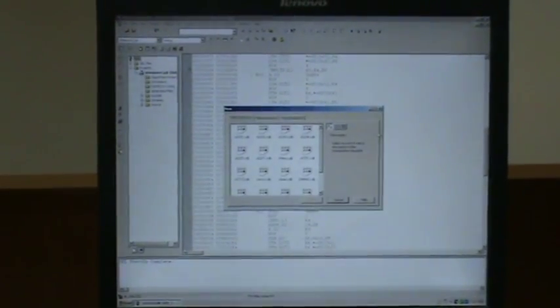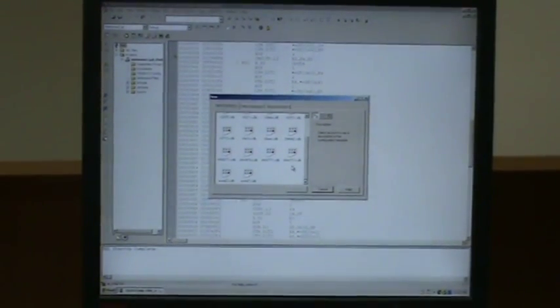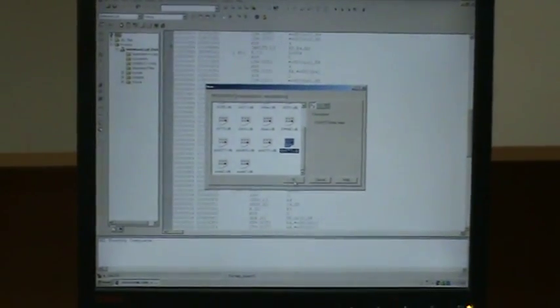So how do we include this DSP BIOS configuration in our file? First click on File, New, okay, start. Now the next step is DSP BIOS configuration. Click on File, New, DSP BIOS configuration. We have to select our particular DSP kit, that is DSK6713.cdb. After that, click on OK. So it's a configuration file.